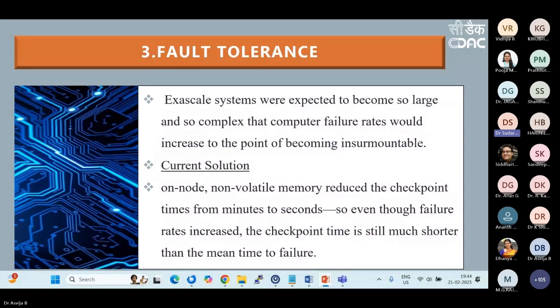And as a hardware system itself, we already provide in most of the HPCs, by design, redundancy at multiple levels. For example, the Param series of supercomputers that we have in India under the National Supercomputing Mission, depending on the capacity, in most cases have two levels of UPS. One is for critical operations, and then there is one for the entire system. Behind the two UPS, we have generators as a standby, and then we have two power supplies from the utility, which means we are looking at three layers of sources: UPS, generators, and the regular power utilities serving the power. So there are three levels of supply itself.